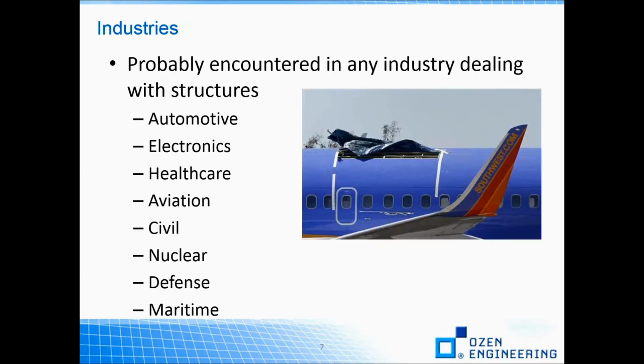So once again, we will be talking more on parameters like stress intensity factor and the J integral. At this point, it is only important that fracture mechanics calculations provide a new set of parameters for calculating and assessing fracture failure, and these depend on material behavior, whether we are working with linear elasticity, plasticity, creep, or any other behavior.